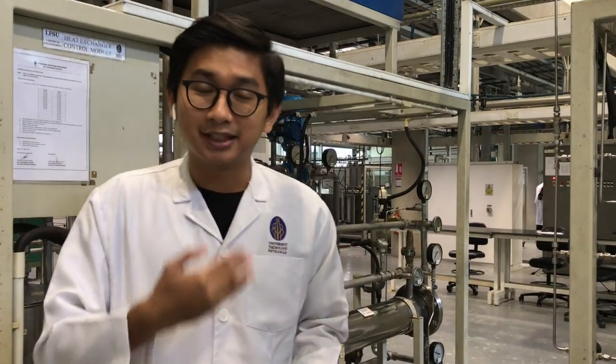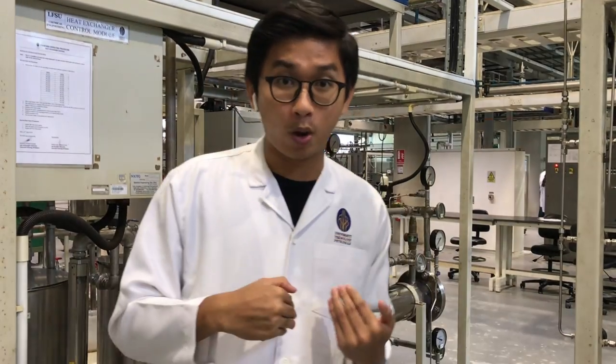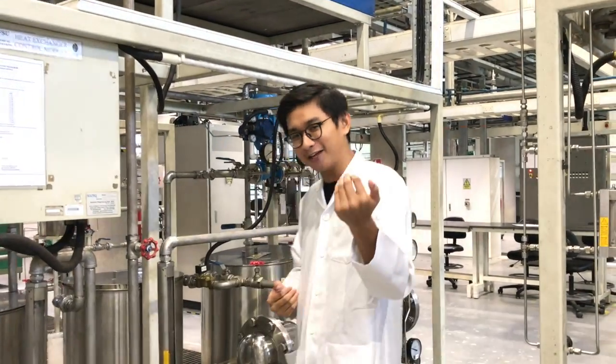And for your information, what happens if I increase the integral time, which is the I value? Once we increase the I value, the response time will be lower, so it will be faster. But for the D value, which is the derivative time, once we increase the derivative time, the response time will also become faster.